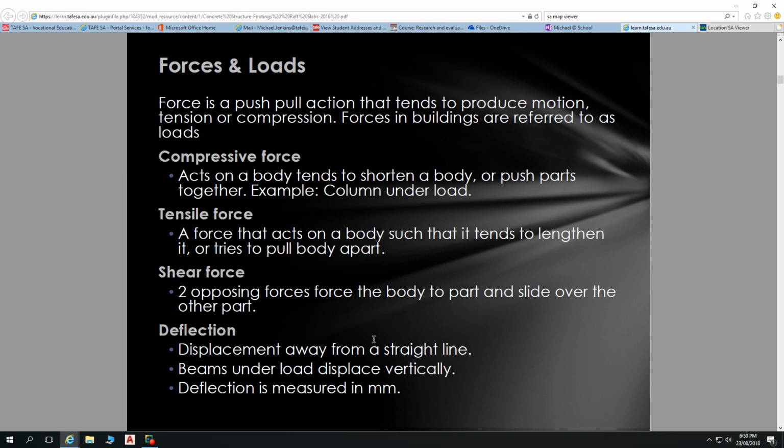You're going to have that little bit of deflection, but you're not going to see it. Also, within your roof, you're going to have deflection of particularly pitching beams, where you've got a major beam, a strutting beam, in your roof that's helping to strut up a roof that's taking a lot of load. That's going to deflect, but no one's ever going to see it because it's hidden in the roof.